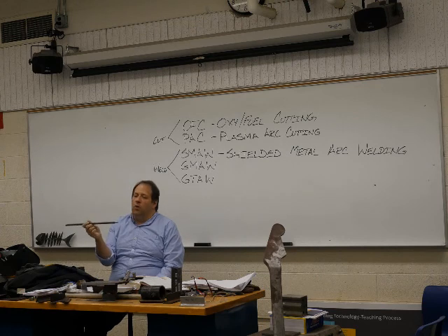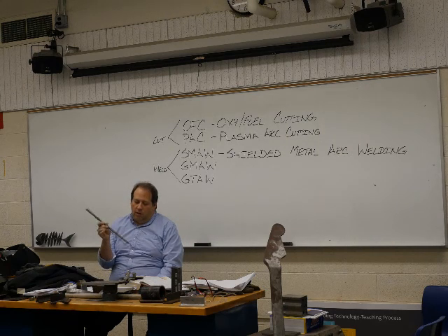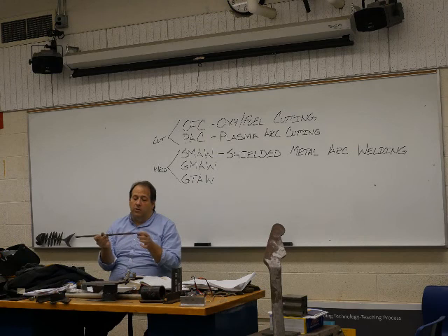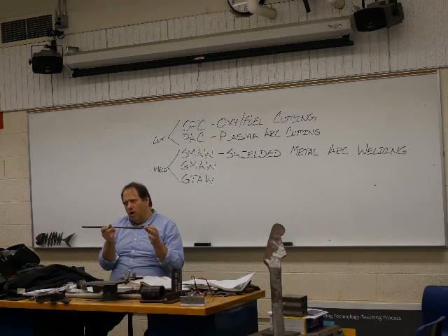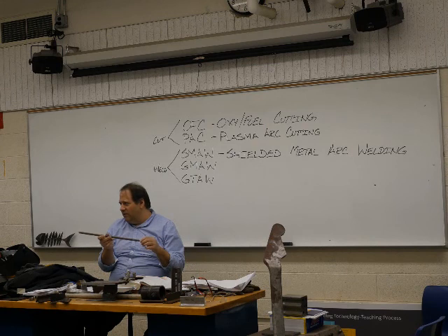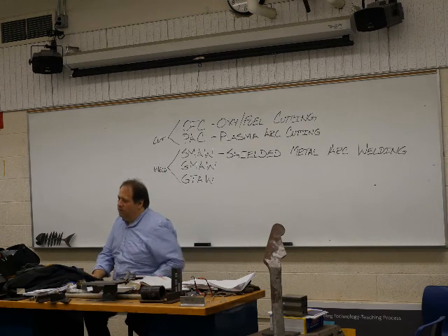So this is an arc welding rod. This is an electrode. It's also our filler metal. So this would be what you would use to do some welding with. Back in the day, back in the late 1800s or so, basically they had no coating on it. It was just bare metal. Didn't get very good welds. They would actually connect this up to batteries, use the amperage off the batteries to do the welding. It wasn't even running off of a generator or something like that. So not that good back then. They were still kind of perfecting the process.